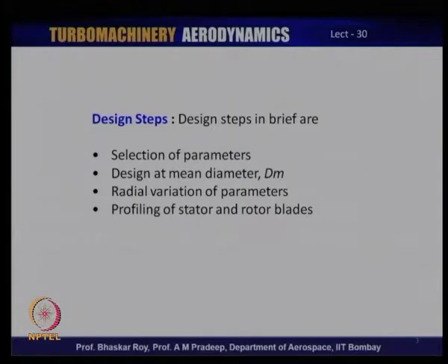And the design finally would need to end with profiling of all the sections from root to tip of stator and rotor blades of all the stages. We will go through the steps of designing a particular rotor, and in the process look at how the stator is put together.